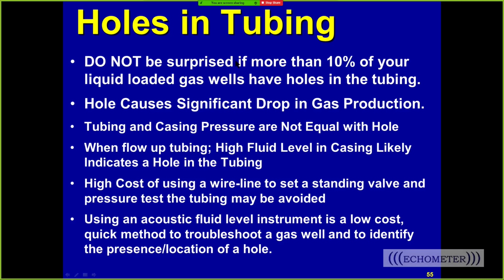So what do we know about that? Well, the operator that found these holes found that 10% of 150 wells that they didn't expect to have holes in tubing had holes. And so don't be surprised if 10% of your wells have holes in tubing and you don't even know it.